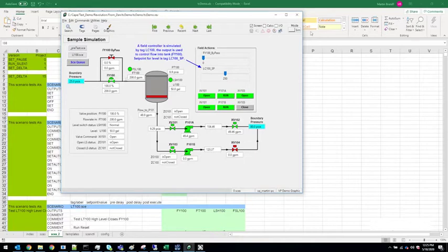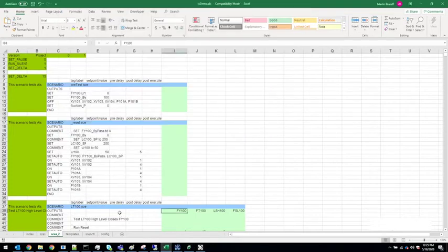The test compiler allows for rigorous testing of a user's safety and control logic. It allows for multiple scenarios that test cause and effect matrices to be quickly set up and tested, while providing documentation that can be used for test verification and proof of compliance. Testing processes can be automated to ensure efficient testing, fault identification, subsequent rectification and retesting. In addition, these scenarios or cases can also be readily executed sometime in the future, in the event change is made to the control logic. This helps demonstrate that the changes being made have not affected the integrity and function of the original control code.